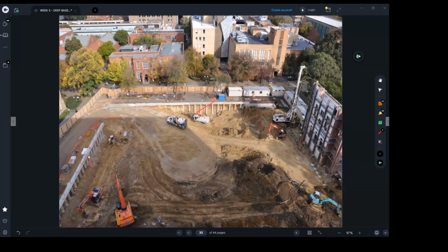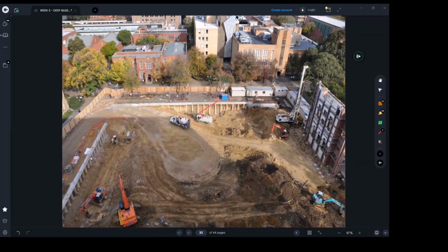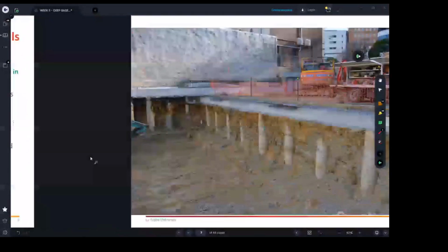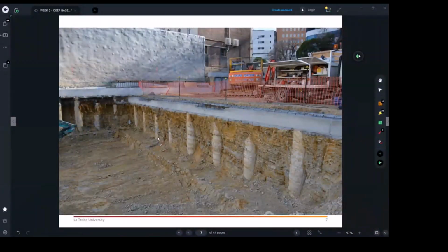They started excavating. And okay, now how deep do we go? This is again up to the soil engineer and instructions. Typically we go 1.5 meters deep only. Let me jump back to the first picture because we're going to come to this project later. So what I was trying to show you here, in day one, we drill holes, excavate, place concrete, place the steel cage, then build our pile cap. Yeah, this is a pile cap.